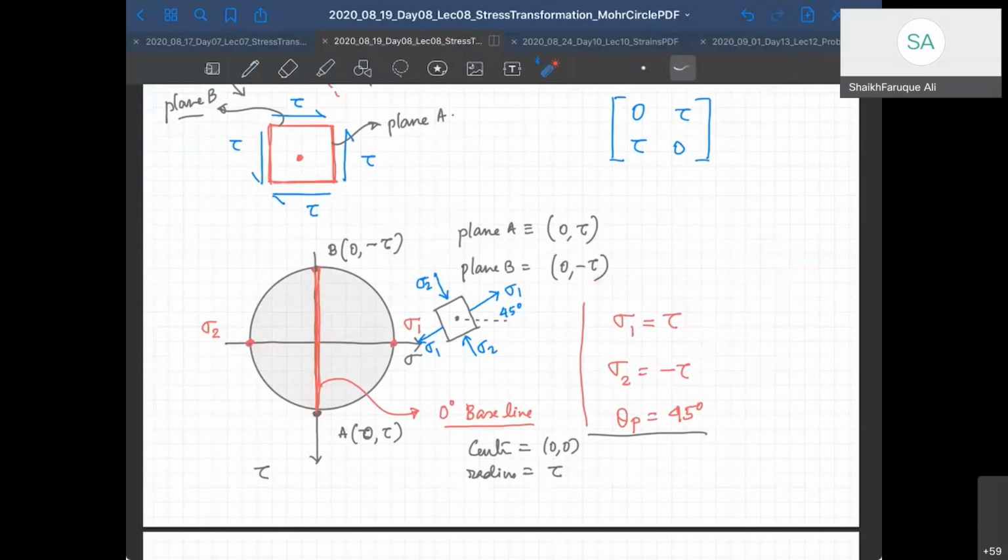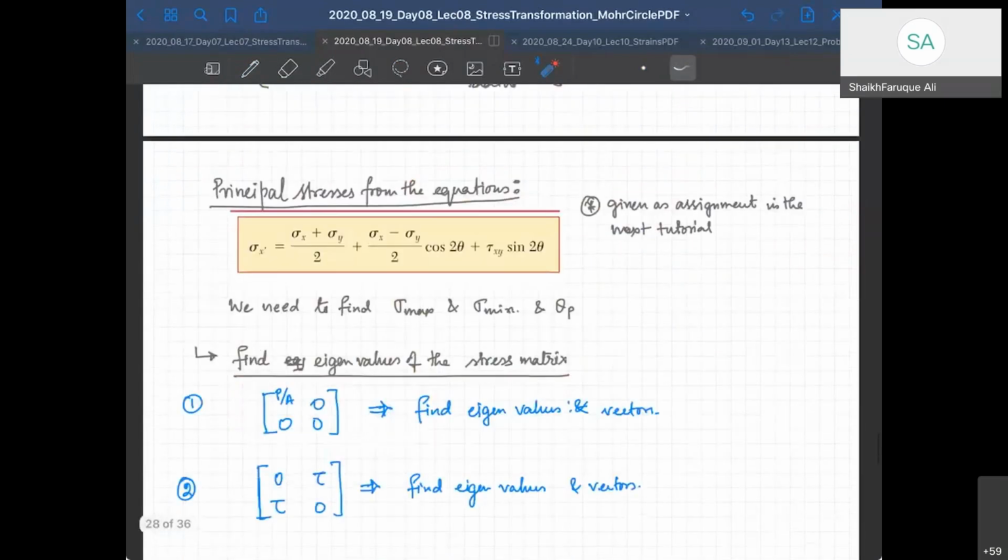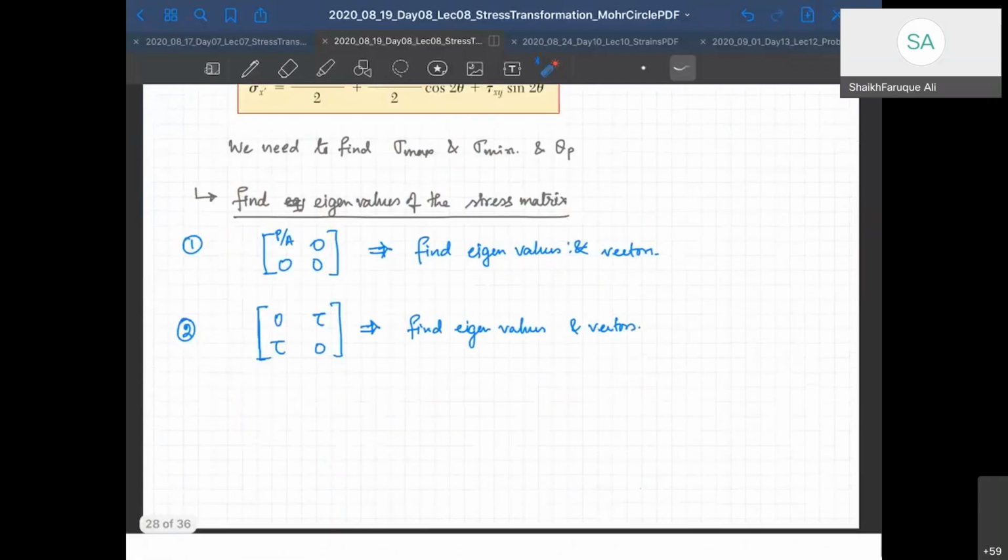Yes, so it's matching, right? Very good. So with that also, for 3D material stress, it becomes very easy to find principal planes and the principal values of the stresses just by finding its eigenvalues and eigenvectors. So one of the applications of eigenvalues and eigenvectors in matrix analysis, in continuum mechanics, is finding principal planes and principal directions. Okay. All right, very good.